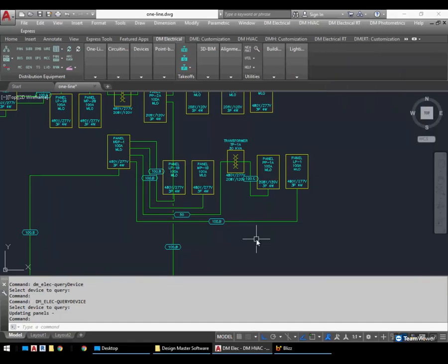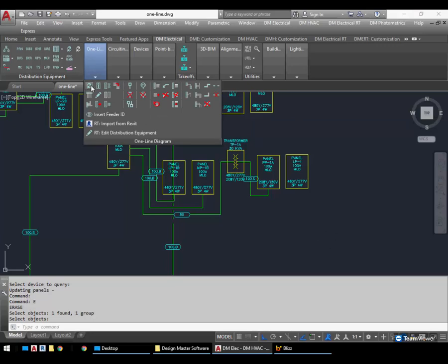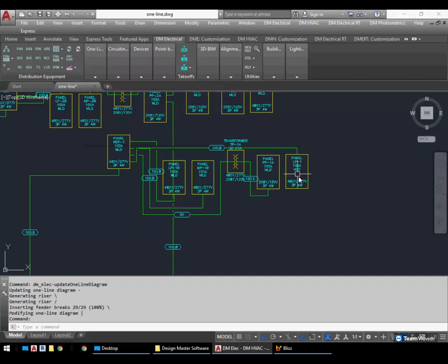nothing's going to change because it's already on the drawing, and once something's on the drawing, we are not generally going to make any changes to it. So we assume that feeder's where you want it, that panel's where you want it, we're not going to touch it. But if we get rid of the feeder, so it's not there, when you do an update, we'll see that it's missing, and we'll put it in, and since we're putting it in automatically, it's now going to come in from the top. So if I do the update, you'll see that we put the new feeder in, and this time it's coming in from the top for that one panel. So you could go and, maybe you do a generate, you see which panels aren't coming in the right way, you can go change a bunch of them, maybe erase the feeders, and have it regenerate them for you automatically.